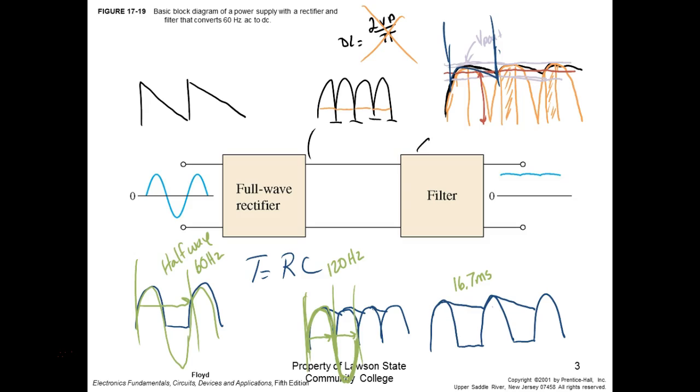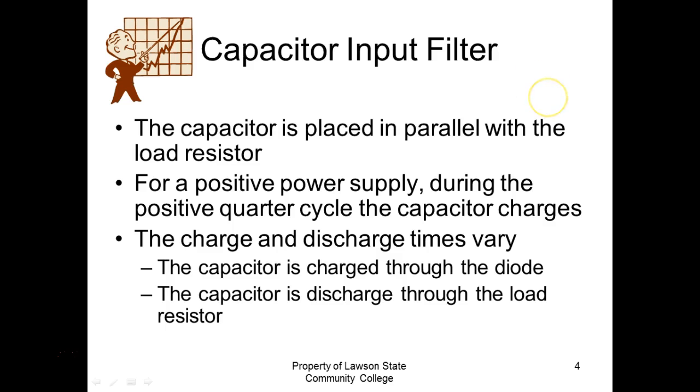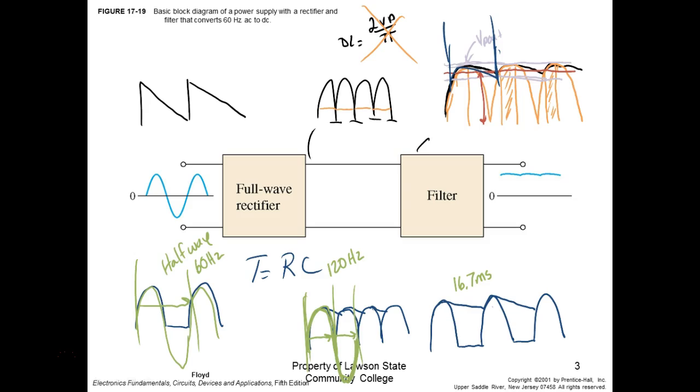Now, this is the time, how long your capacitor is going to have to run the load. But somehow I've got to get V into this formula, because what we're trying to calculate is the ripple voltage.